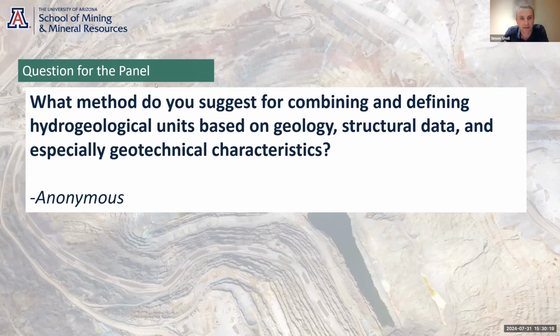And that might define how small a resolution you go down to on the layering of certain aspects of your conceptual model. You'd still describe those layers as part of the conceptual model, but you wouldn't necessarily single them out as multiple hydrogeological units. You might lump it as a single hydrogeological unit, but describe it with some sort of anisotropic characteristics. So I like to keep things simple if I possibly can.